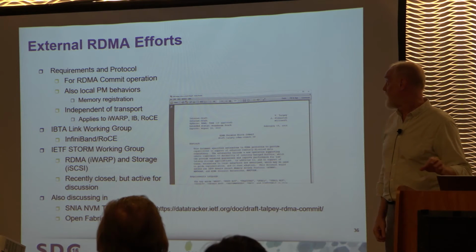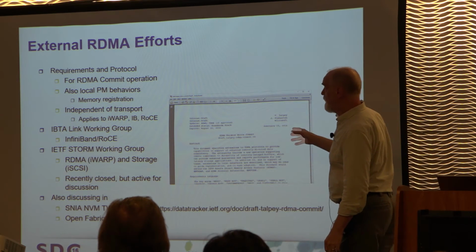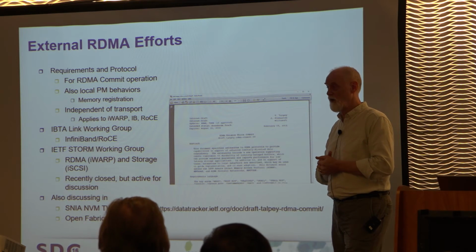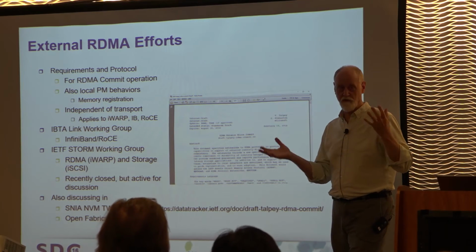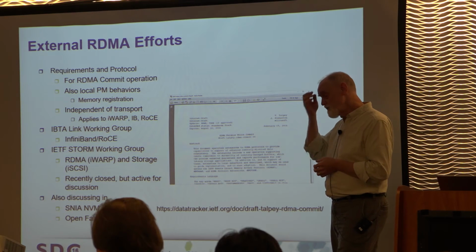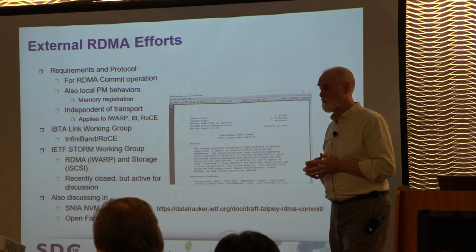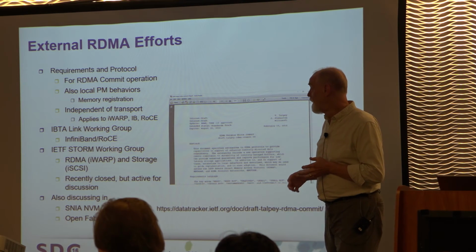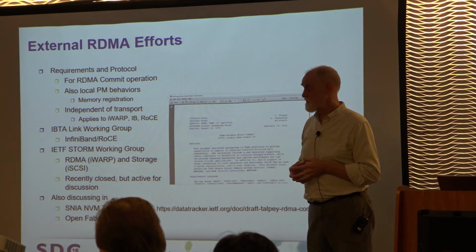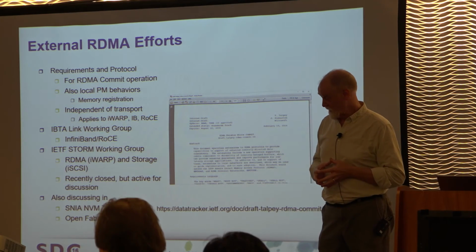And finally, external RDMA efforts. We mentioned this. The requirements in the protocol need to be done in a very broad way through standards bodies, right? We need everybody to know what to do and to be able to build interoperable and useful implementations. So this moves to various standards organizations. I didn't actually mention the PCI Express folks here, but the PCI SIG is an important one as well. IBTA Link Working Group, specifying InfiniBand and RoCE protocols for this. The IETF STORM Working Group, which unfortunately I was the co-chair of, is recently closed.